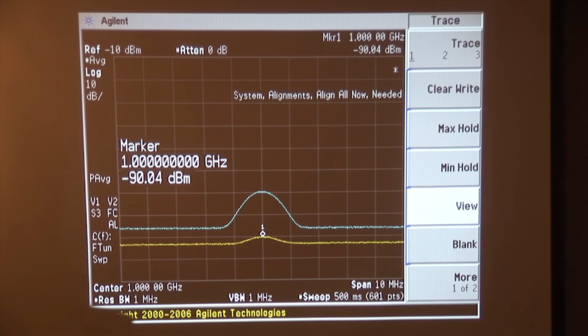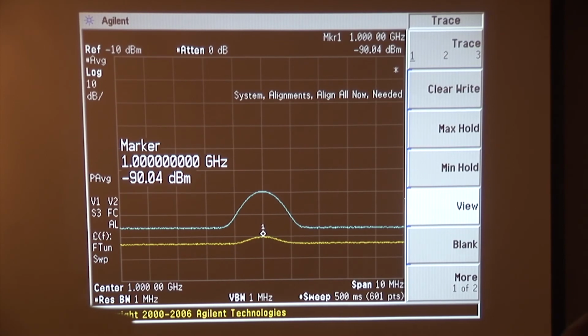So far, so good. Now we trade out the first amplifier. We're going to go to the second amplifier, which, do you remember what the noise figure was on this one? It's still about like 4 dB, I think. It's about the same noise figure, about 4 dB, but more gain, because some people think you can't have too much gain. And I'm going to show you that you can have too much gain.